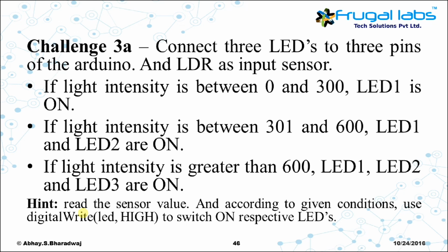The hint is as follows: you need to read the sensor value and, according to the given conditions, use a digitalWrite LED, HIGH to switch on the respective LEDs.